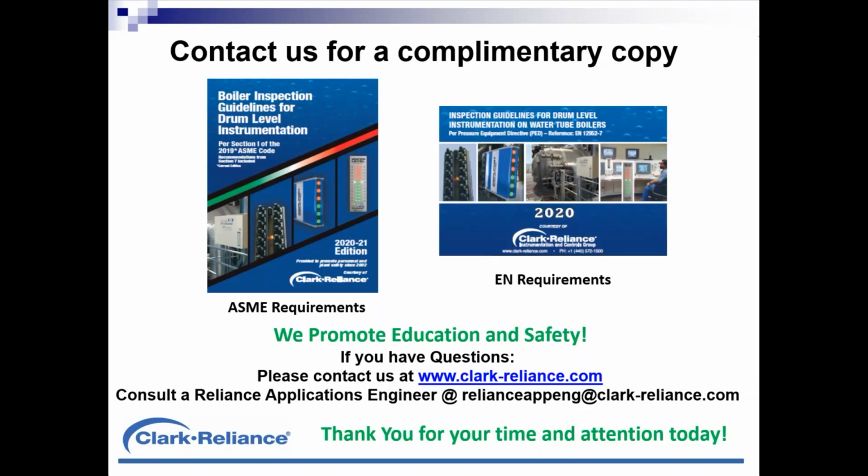That is correct. And that's why some of the need for blowdown on this equipment, as we mentioned, and we have that video available to show people how to do that appropriately. Also, to maintain water quality, there'll be continuous blowdown systems, often on many drums. The water chemistry is getting a bit out of our area of expertise. However, the American Boiler Manufacturers Association does have a document about water quality. So that's one resource for our attendees today.